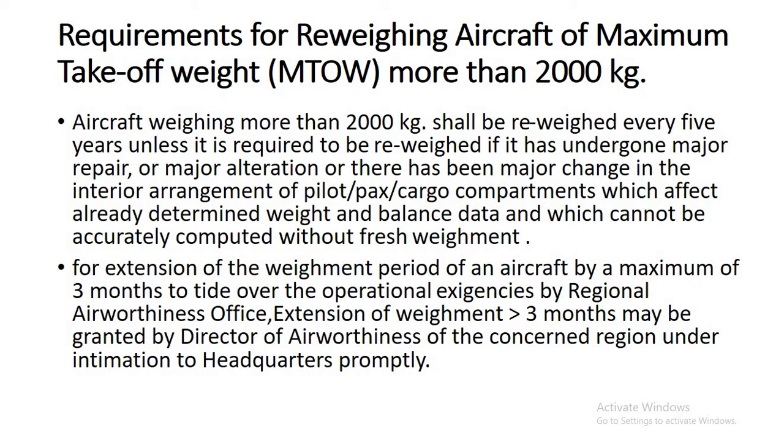But before this 5-year period, if you have done any major repair, major alteration, or there has been any major change in the interior arrangement of pilot, passenger, cargo compartment, which will affect the already determined weight and balance data, and that data cannot be calculated theoretically, then you have to go for a reweighment earlier than this 5-year period.